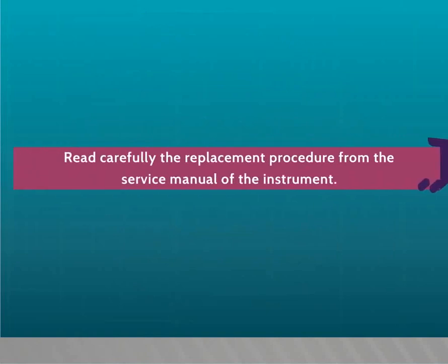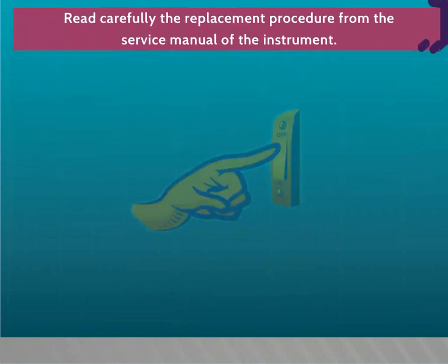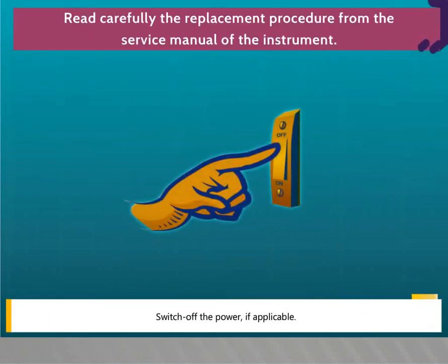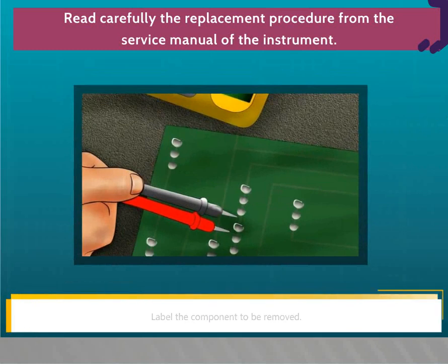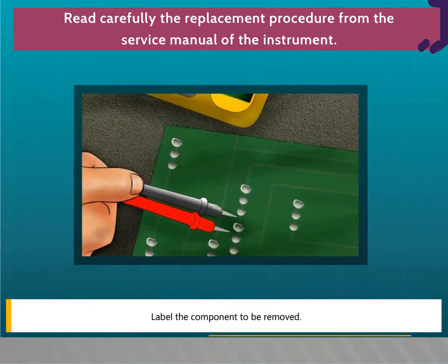Read carefully the replacement procedure from the service manual of the instrument. Switch off the power if applicable. Label the component to be removed.